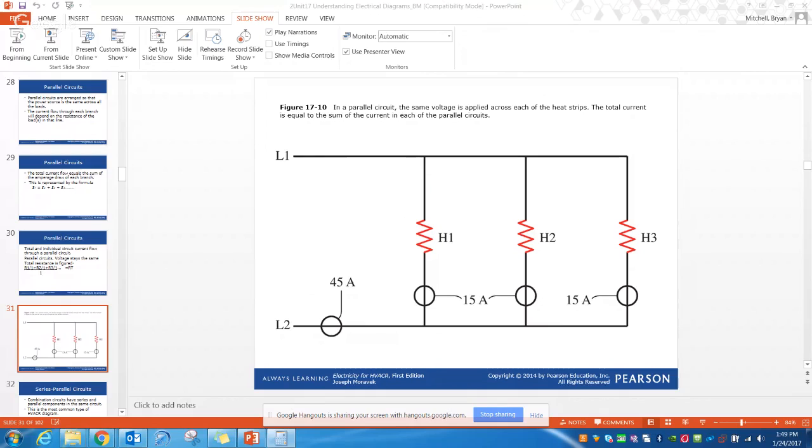And what I'm wanting to illustrate to you guys on this is that the total resistance in a parallel circuit, RT, is less than the individual resistance, even of the smallest resistor, less than R1 or R2. So the combination of those is going to bring the whole unit down. Everybody clear on that? I'm surprised that you guys didn't do this, and I wish I would have had you your first semester, because we would have.